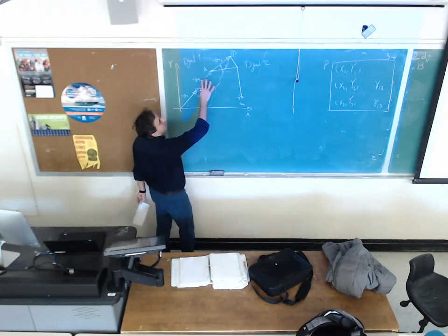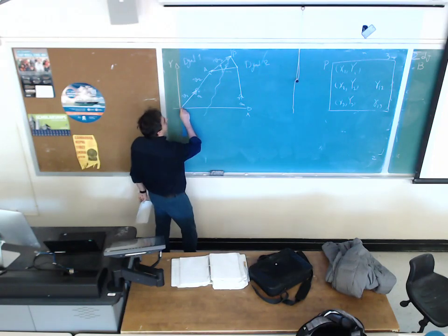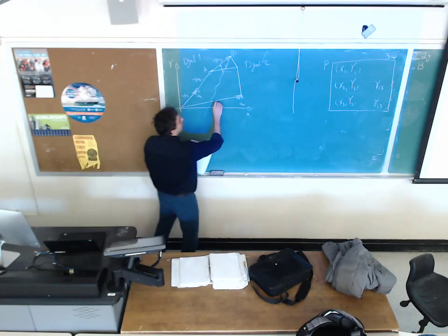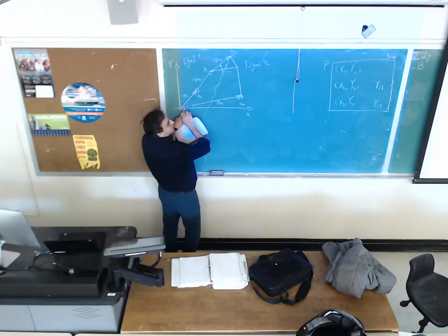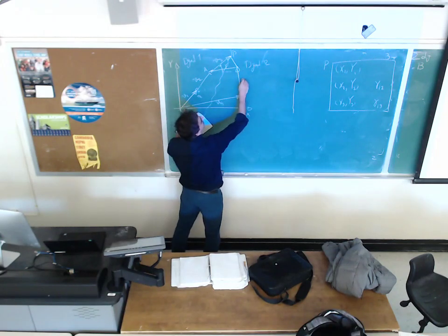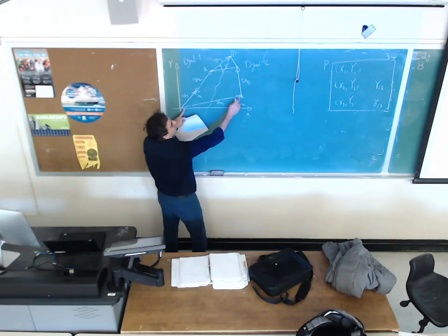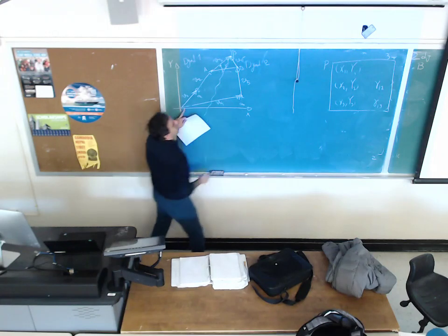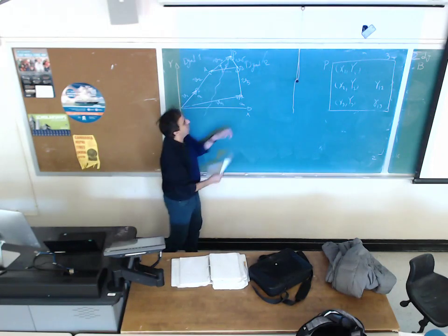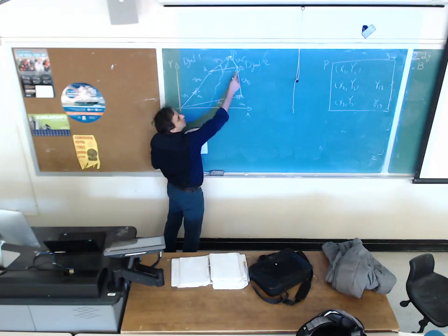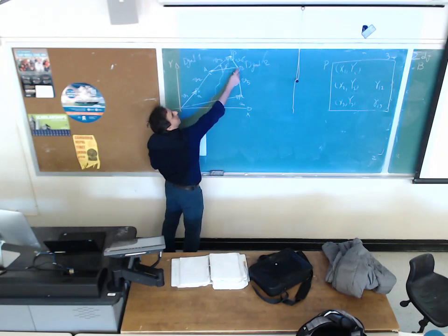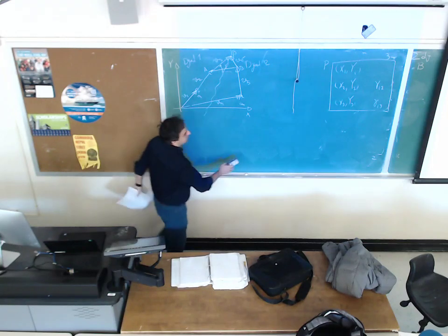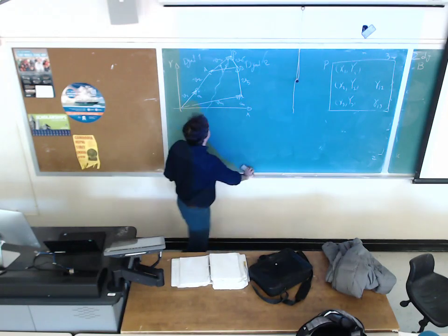After we are done with diad 1, we define V4, the vector connecting the origin to O4, V5, the vector connecting O4 to this point, if I call it V, and V6. By working on diad 2, we are finding the location of O4, the location of V, and then this length. And we are done with the motion analysis.